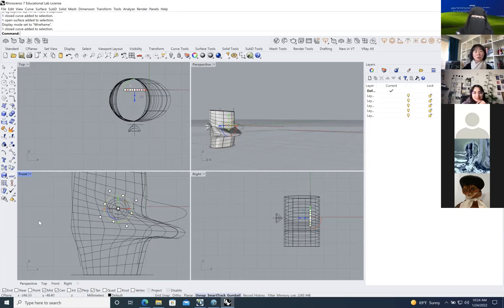So what I'm going to do is skip the projection, because projection is to project whatever fancy thing in the universe onto a curvy surface and generate the line on the surface, because we cannot draw on a curvy surface. But if we just want to cut a hole, we can skip the projection. We just use trim. So I'm going to show you, right here on the front surface. And then I'm going to use trim.